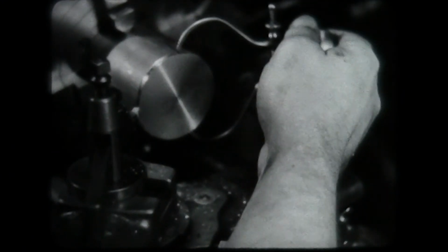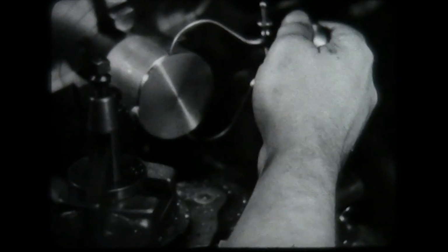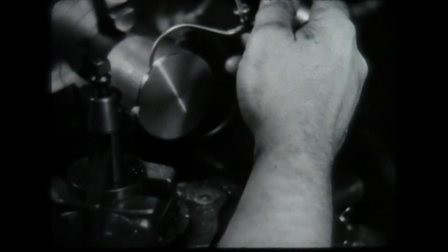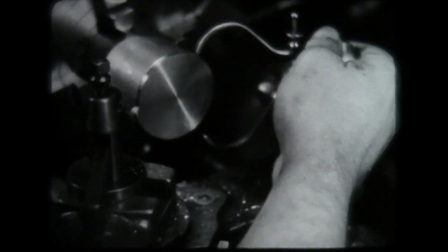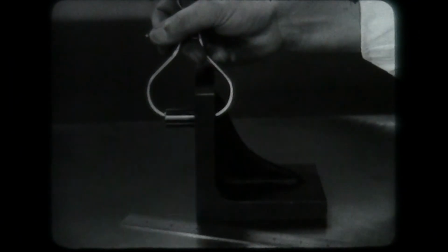The outside caliper is often used to check work on a lathe. The operator uses care not to force the caliper, which would be sure to result in a false measurement. Outside calipers are frequently used to determine a measurement by transferring the calipers from the work to a rule.